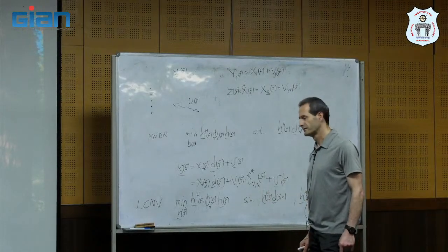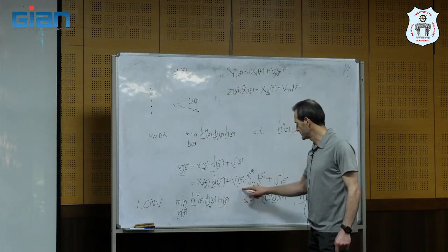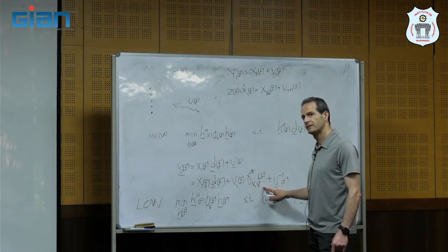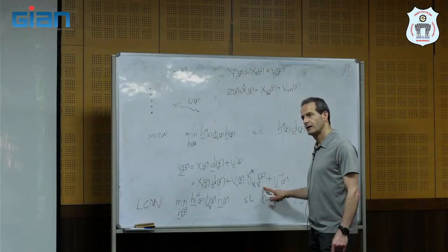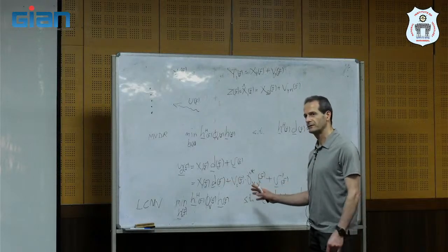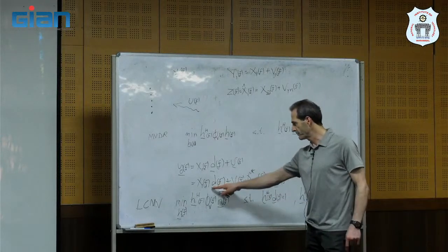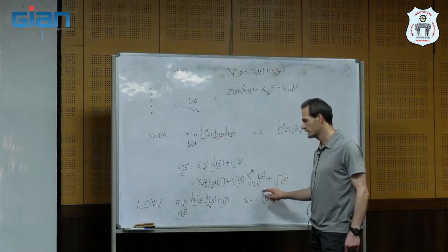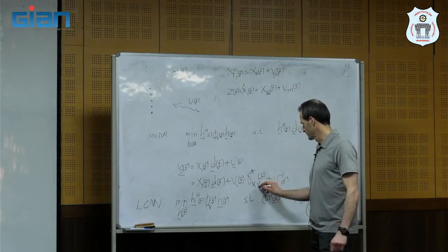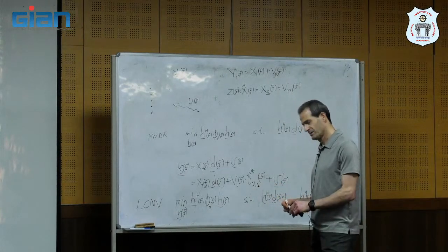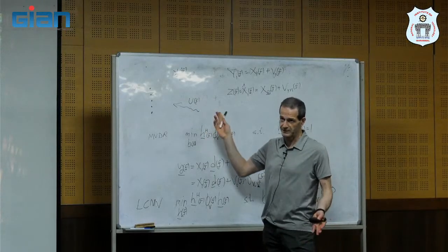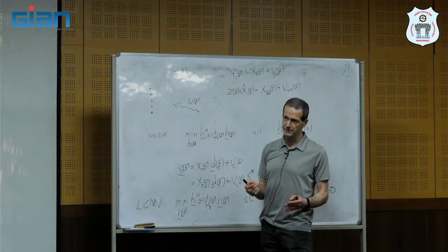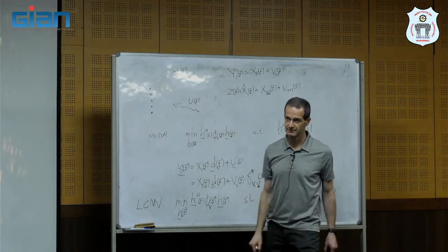So you tell me, if this is the same as this, what does it mean? It's on configuration of the array, but the array is the same for these two components. So you have an array. If D equals this, what does it mean? It means that the sources, if they are both far-field, they come from the same direction. If they are near-field, they are in the same position.